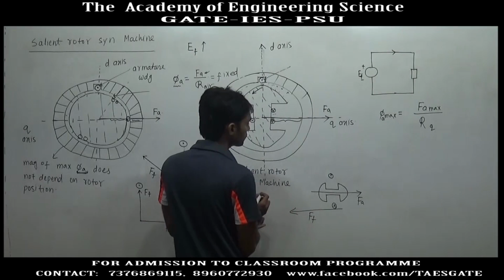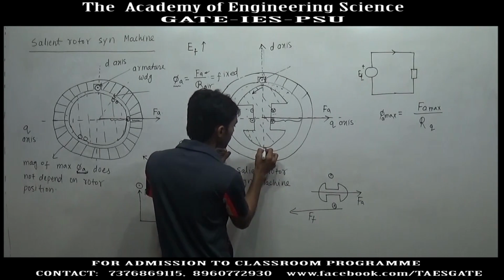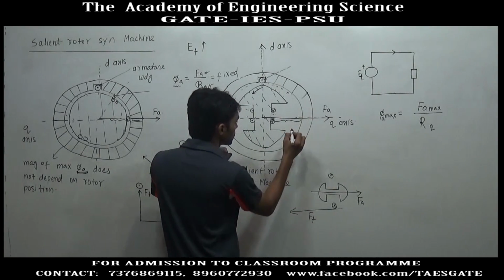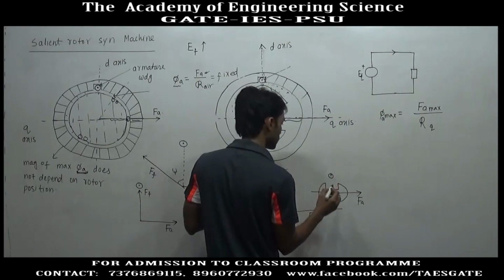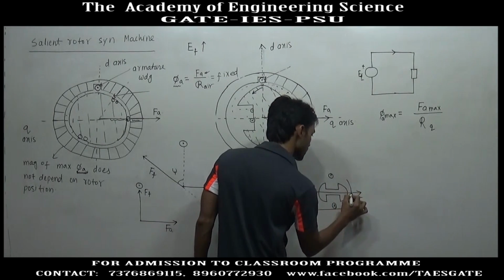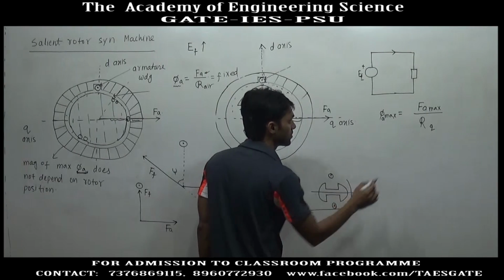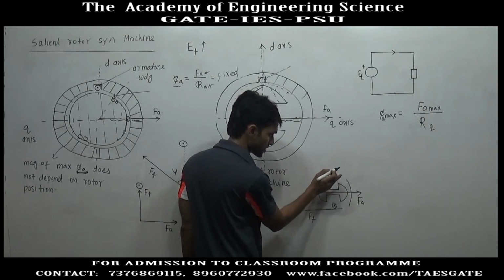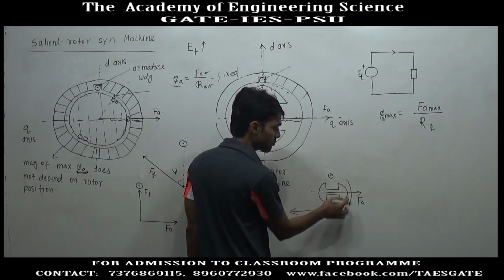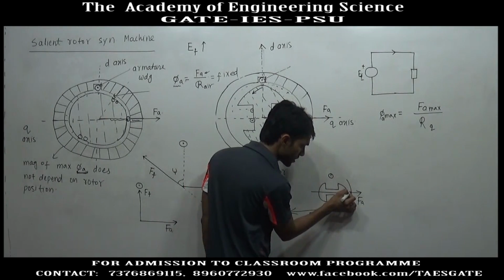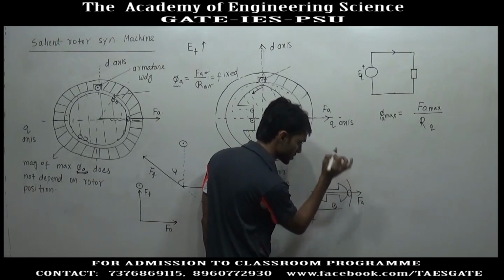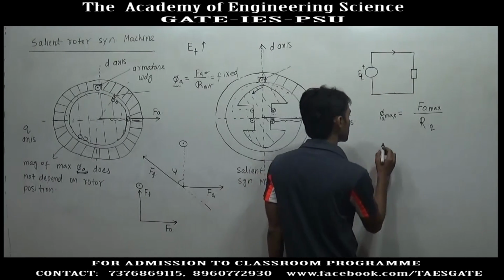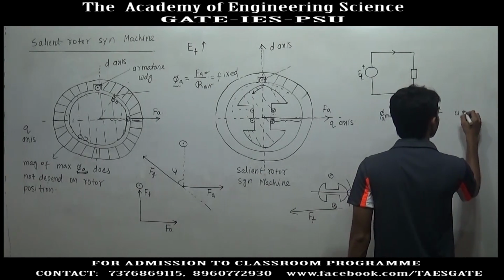Now, this point will come here. This is the stator part. The same maximum MMF, because the same maximum armature current will be induced, will feel reluctance due to only this much air gap. So, this is the unity power factor case.